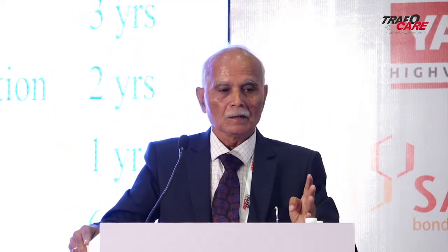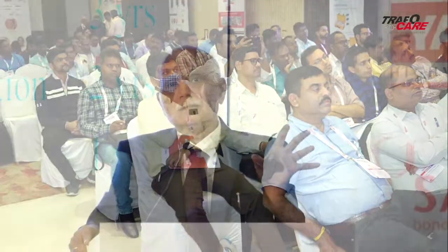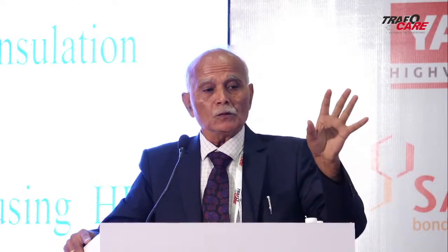So we have decided that if the ppb levels are less than 100, it's a normal transformer and its insulation is perfectly healthy. 250 to 1000, that means the degradation has started. That means moisture has permanently entered into the system and started the degradation, and it is not going out due to the thermal cycles the equipment is undertaking. And if the values are more than 1000, then the transformer is highly unreliable. And if it is greater than 2500, the transformer can fail any time. So we can have the assessment and take the remedial or replacement actions so that we can keep the transformer in line without allowing it to go for catastrophic failure. Next slide.